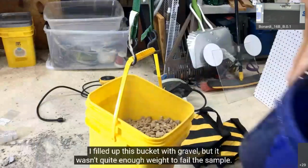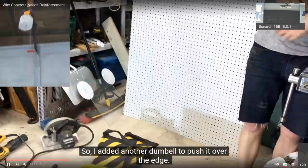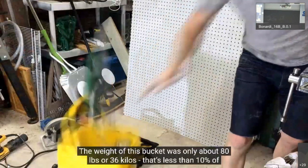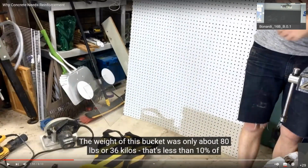He increases the load progressively, and the sample fails at a weight of 33 kilos. Before it was 450. So that's why we were saying before that concrete behaves very well in compression, but performs very poorly in tensile conditions.